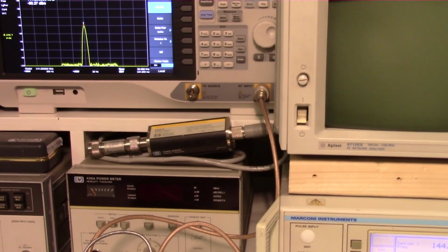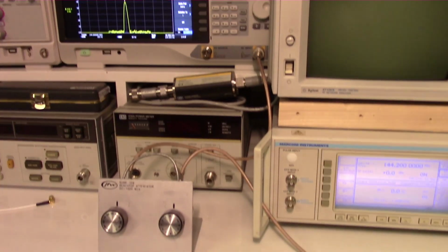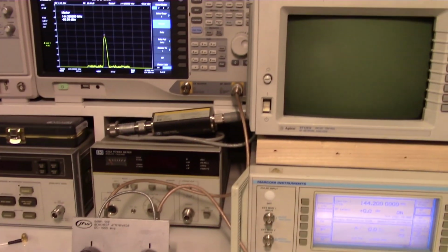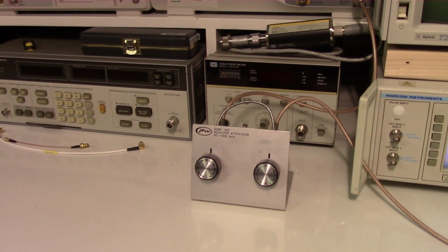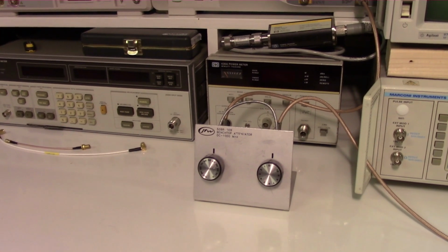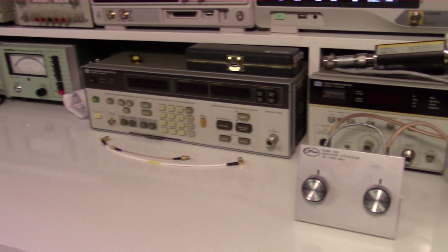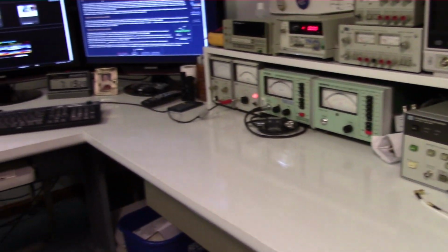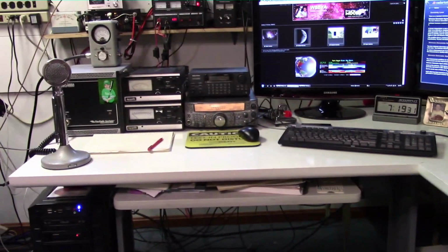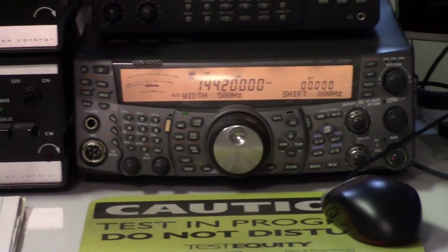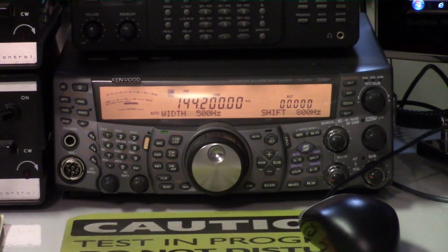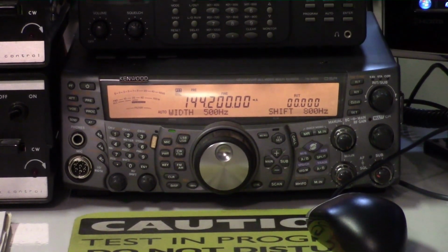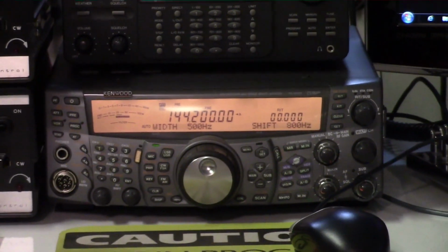So what I'm going to do now is disconnect the RF signal, and rather than going to the spectrum analyzer, I'm going to connect up a cable, a double shielded, probably RG223 cable, and we're going to run it over to the TS2000, right to the antenna port connector. In this case it's going to be a PL259 connector. And let me go ahead and set that up, and we'll show you just how easy it is to measure the MDS.